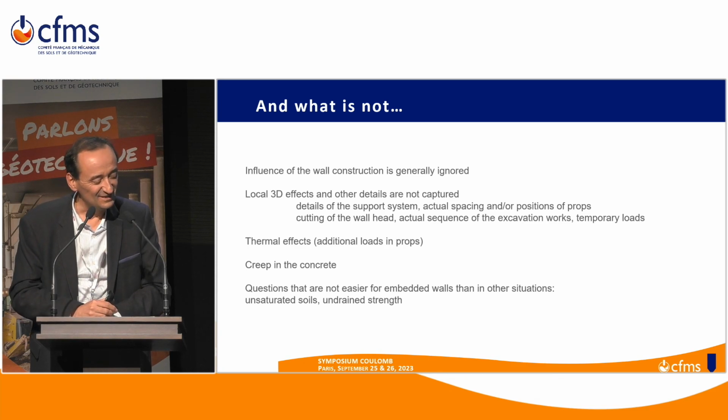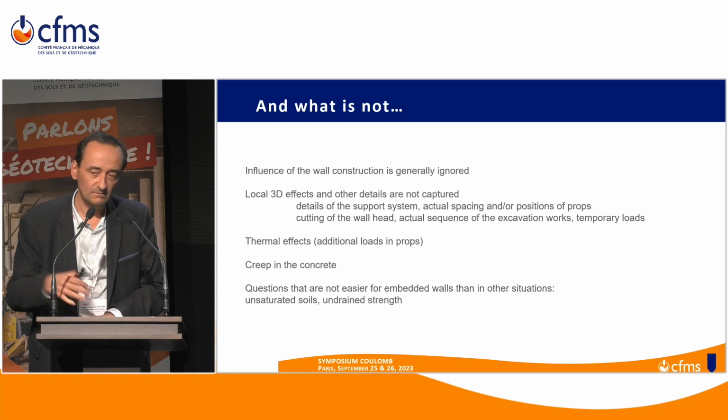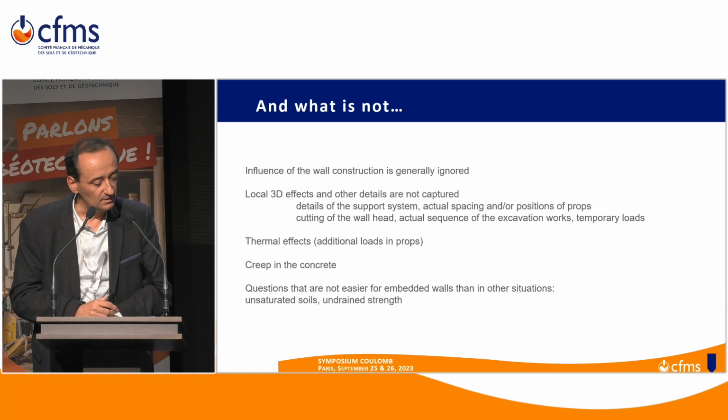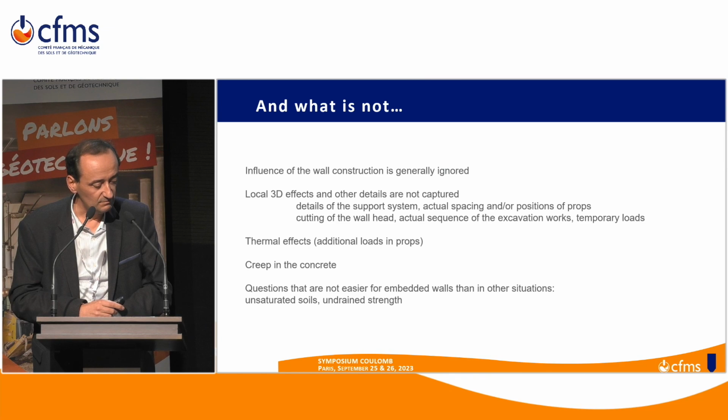Some key steps of the construction, like the cutting of the wall head, are generally not discussed. And in a more general way, the details of the actual sequence of the works, possible temporary loads, are not really described. Thermal effects are rarely discussed, and they may induce additional loads in the props. Effects such as creep in the wall are not discussed, well, in most cases.